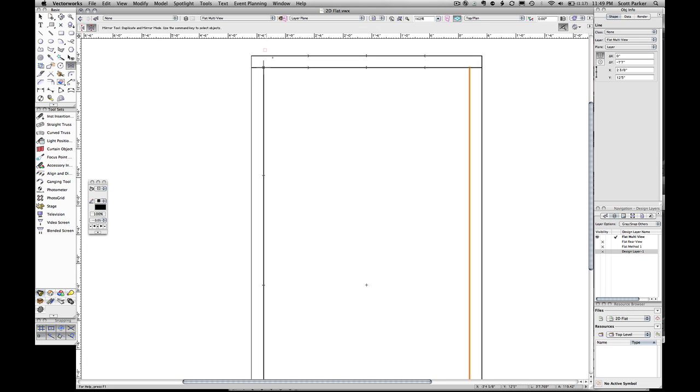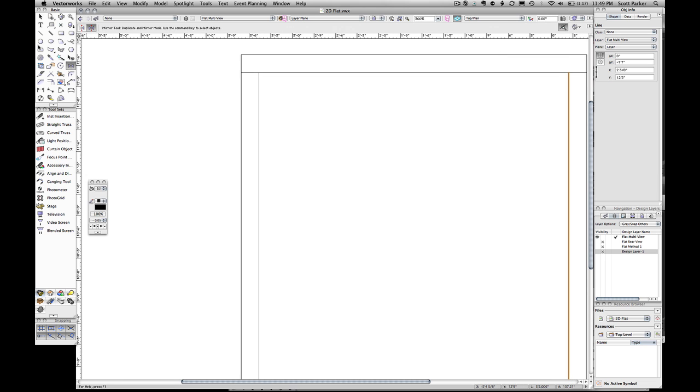There we have it. Now I'm going to draw my corner block. I'm going to draw a 9-inch line going this way. For the one edge, draw another 9-inch line going straight down. 9, enter, click. Now I can take a diagonal line from that one and find the end of this one that I just made. It's a 45-degree angle. Click that one. This has 3 lines now.